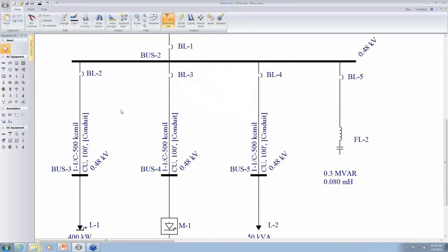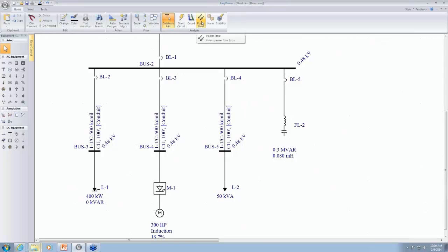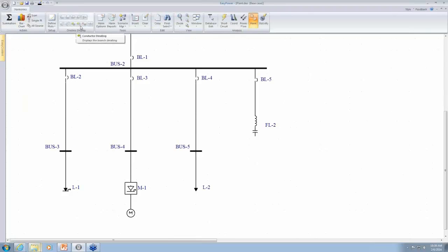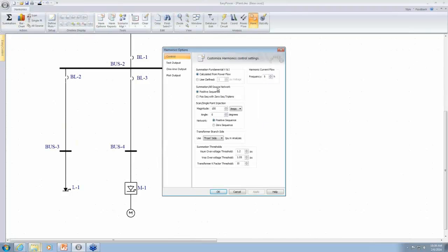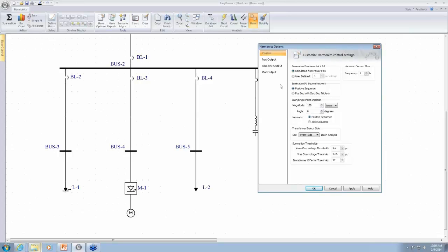Now in terms of looking at power flow results, if you do not have the power flow, then all the percentage that you calculate is based on a certain user specified value that you get. So always make sure that to get better results, use power flow for summation calculations.